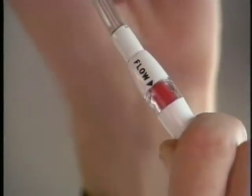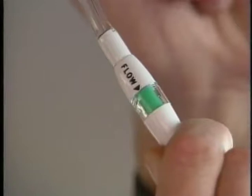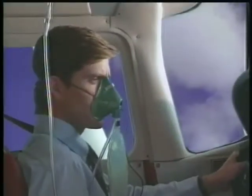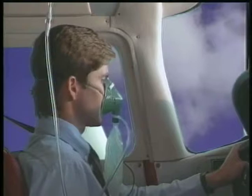The flow indicator shows that oxygen is flowing to the mask. This device is simply a spring-loaded check valve. When the oxygen is flowing, the pressure overcomes the spring and deflects the colored valve toward the mask. The rebreather bag helps conserve the oxygen supply by mixing the oxygen with outside air.